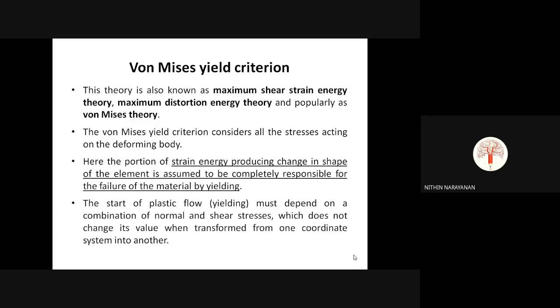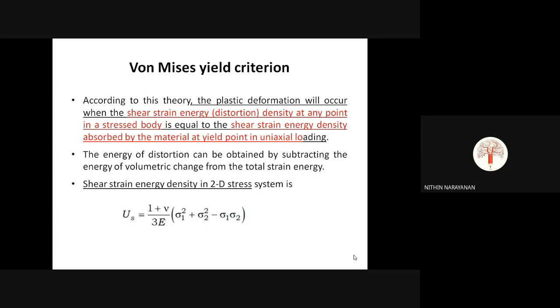The start of plastic flow, otherwise yielding, must depend on a combination of normal and shear stresses, which does not change its value when transformed from one coordinate system to another. So according to this theory, you learn this by heart.